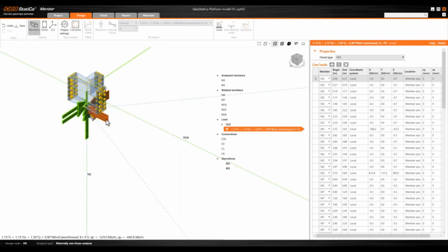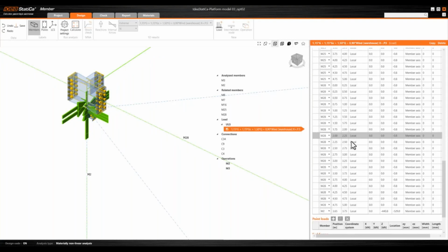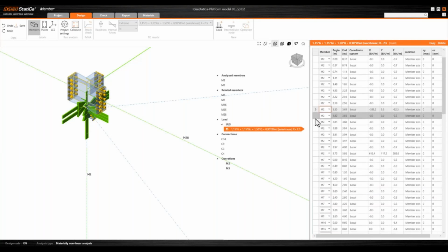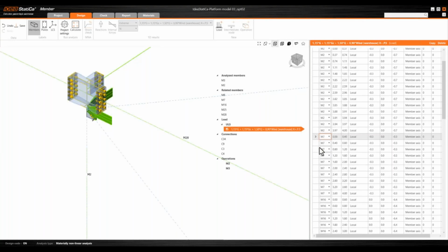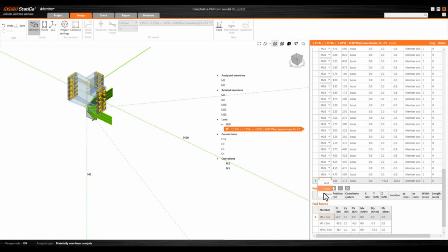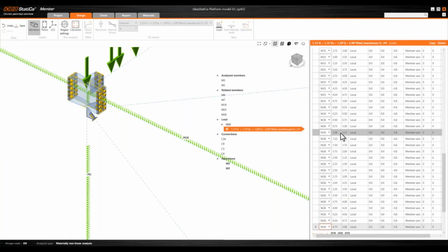Another thing we need to look at is loads, because we see that there are some load concentrations that are probably erroneous. We can detect them in our loads and delete them. So I'm removing this. As I remove this erroneous definition, I see that the rest of the loads come into perspective.